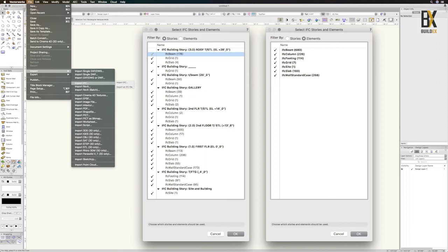that empty file. You can see here on the screen that when selecting the import IFC option, there are two different ways to see the information. What you can see on the screen here is an example of a structural model. Each of the stories that are set up in the Revit file comes into Vectorworks and will be transferred as a design layer.